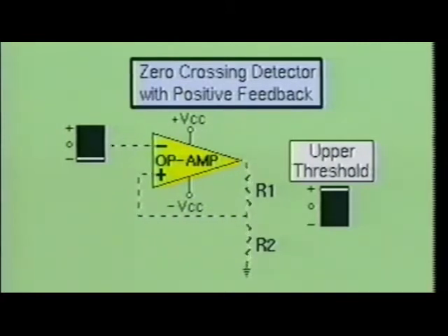When the voltage at the inverting input becomes slightly more positive than the feedback voltage, then the output voltage will begin to decrease in amplitude. By using positive feedback, the output voltage will drop even faster and it will quickly drive the output into the negative saturation region. This results in a more stable switching action when the output switches polarity.